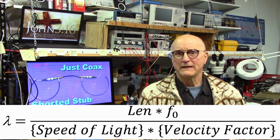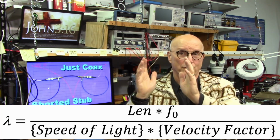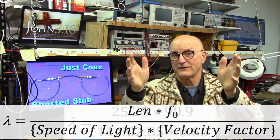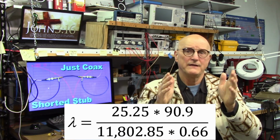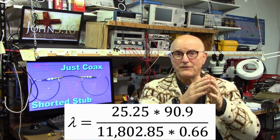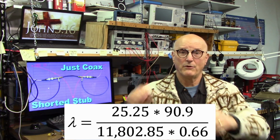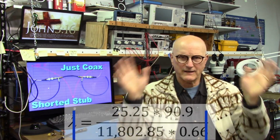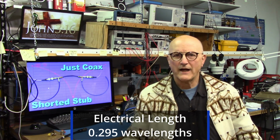Our first step is to determine the electrical length of our cables at the frequency in question. To do this, we use the following formula. The electrical length of the cable is equal to the physical length times the frequency in question, all divided by the speed of light times the velocity factor. So we have 25.25 times our frequency, which is 90.9 megahertz, all divided by 11,802.85 times 0.66. And according to this calculation, our cables, including all of the adapters and the connectors, are 0.295 wavelengths long.